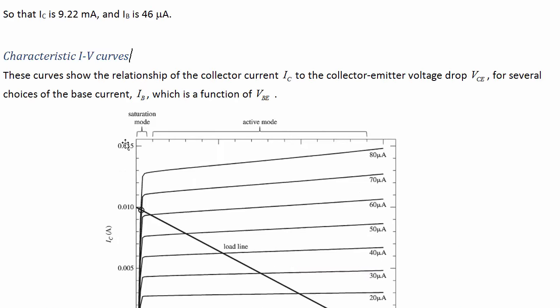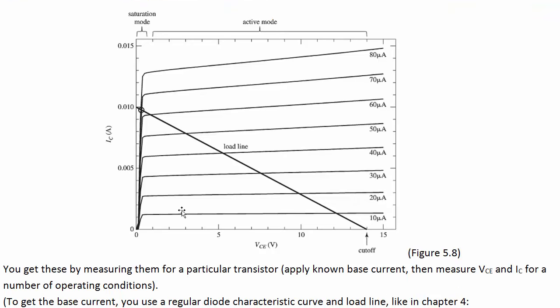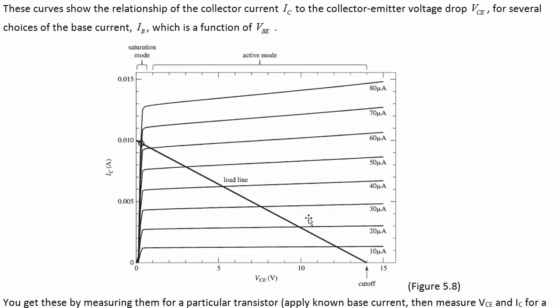You can see, so earlier we described it as if you apply too much base voltage, then we go over into the saturation mode. How the collector actually behaves is kind of a compromise between the transistor parameters in the back and the circuit that it finds itself in, which is going to determine this load line. So the load line here is the collector terminal load line. It's a relation between collector current and collector emitter voltage. And the slope of this is going to be determined by what resistor you've got on the collector side of things.